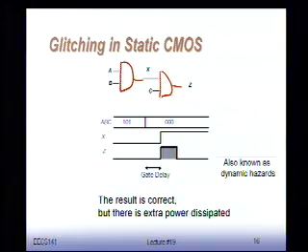As I mentioned, if you look at logic and you do, let's say, a simulation, you probably did the simulation of your large logic function, right? And you look at the waveforms and you probably notice that some of the waveforms in your adder array do multiple transitions. During one clock cycle, you have a node that initially might go high and then go low again, might go high again. Okay? We call that a glitch. From a pure functionality perspective that 1 to 0 transition doesn't do anything, because what really counts is the value that you get at the end of the clock cycle. Right? Some people also call them dynamic hazards.